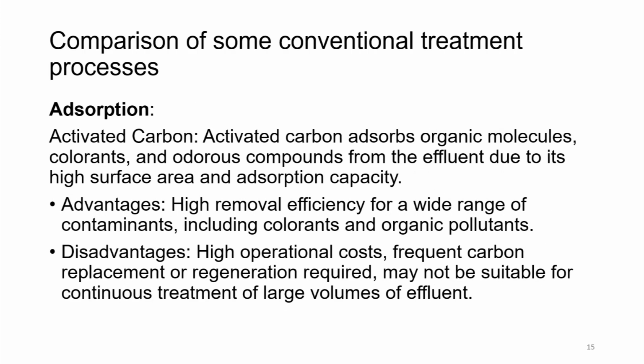Adsorption. Activated carbon. Activated carbon adsorbs organic molecules, colorants and odorous compounds from the effluent due to its high surface area and adsorption capacity. The advantages are high removal efficiency for a wide range of contaminants, including colorants and organic pollutants.